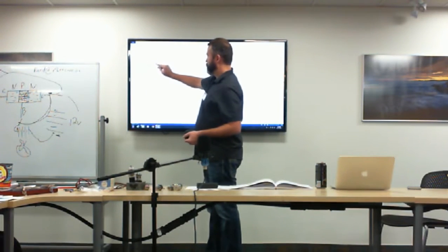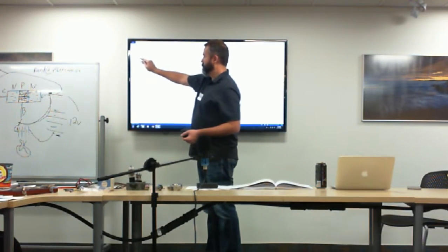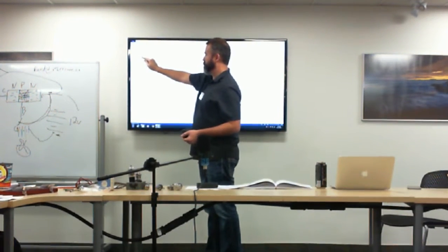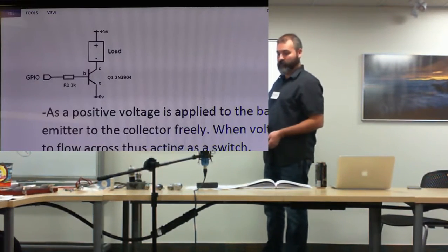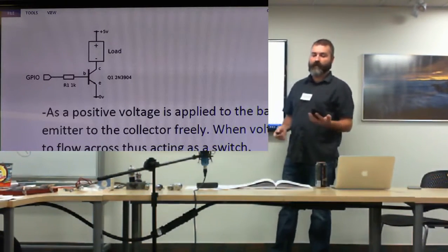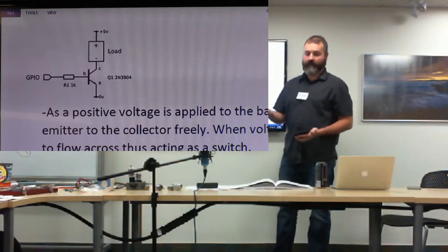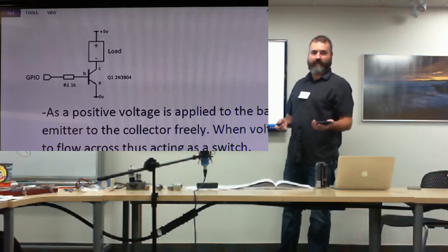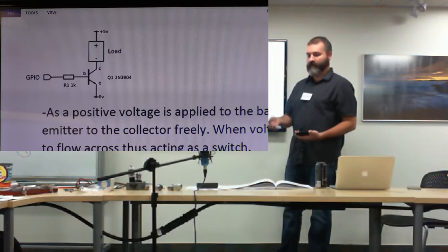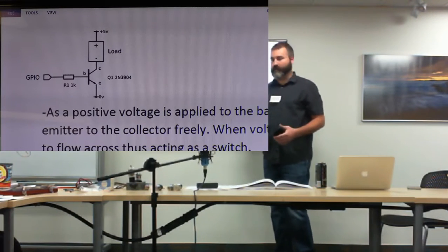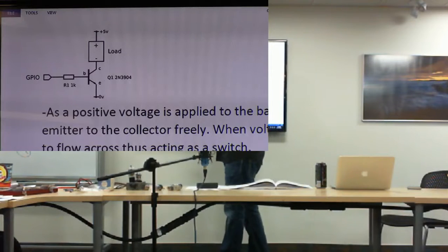You can see the 0 voltage here would be connected back to the 0. There's a positive side that goes in the GPIO. I do a lot of work with microcontrollers, and a lot of the microcontrollers I use are 5 volts. And I want to control something that's much higher voltage. For example, I have a cooling fan, it's 12 volts. If I hook that up to the 5 volt source on my microcontroller, it's going to draw too much, potentially killing my microcontroller. At the very best, the fan won't spin very well. It's only 5 as opposed to 12 volts. So I use an NPN transistor.